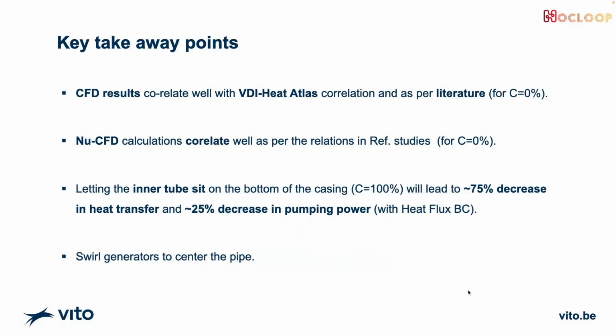So some takeaways. The data for the eccentricity equal to 0 correlated very well with the open literature. And more importantly, if my inner pipe is sitting at the bottom of the casing, we can have up to 75% decrease in the heat transfer and 25% improvement in the pumping power.